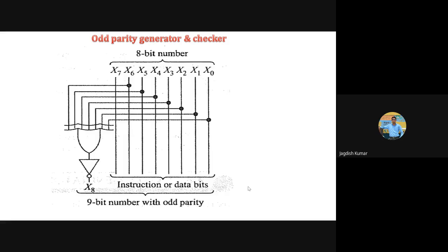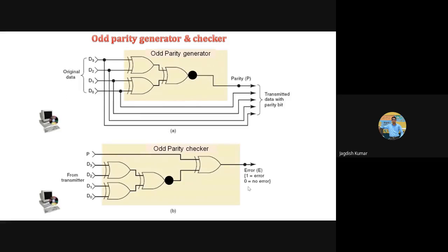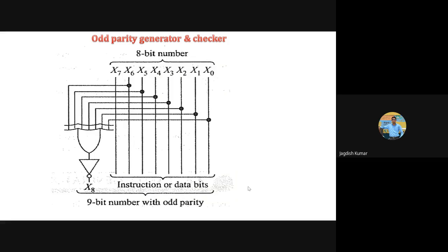Well, now that was a simple case. We had data which is 4-bit, and then the fifth bit was used for parity. Then you may ask, what if the data contains many bits? So you can actually employ an n input exclusive OR gate, and you know how to get that n input exclusive OR gate. We have seen it in the previous slides.